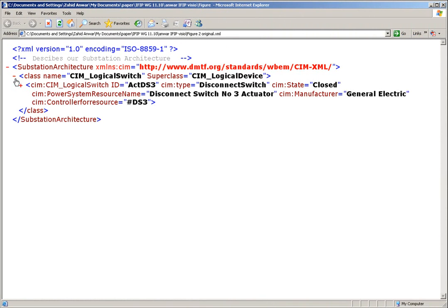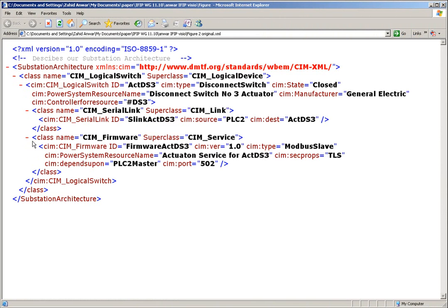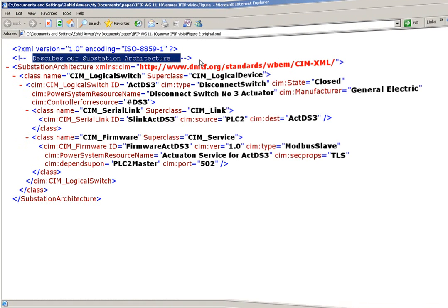The toolchain automatically generates first-order logic predicates by parsing substation network schematics described in the Common Information Model, CIM, or the Substation Configuration Language, SCL, which are standards used by the power industry to exchange substation information.